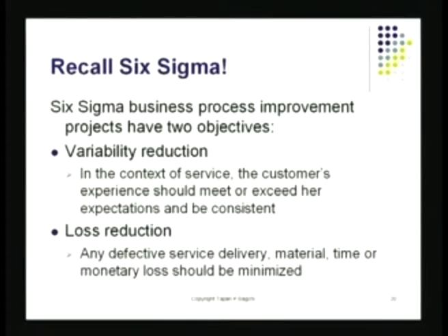That's one thing. The second thing that Six Sigma tries to do is basically, you can think of it, it tries to reduce defects. And it tries to reduce the defects, certainly for hardware, down to the level of parts per million defects, which is like a few defects per million parts inspected. That's the level at which Six Sigma tries to get to. So there is this variability reduction, that's one of the goals.